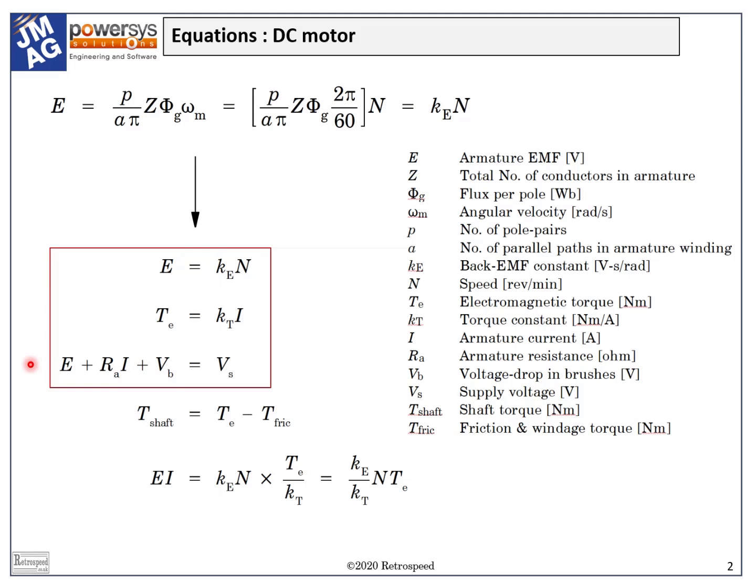These equations form the basis of the control not only of the permanent magnet DC motor but also of the wound field DC motor, which has the facility for adjusting the flux in order to modify the torque per ampere, the generated voltage, and the speed-torque characteristic.